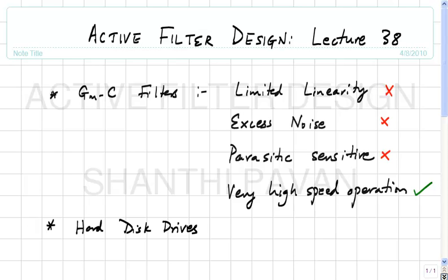So that's one thing. Another thing is that if the disk is spinning at a constant angular velocity, the data rate at the outer edge of the disk will be much higher than the data rate at the inner end of the disk, right. So not only do you have a channel whose bandwidth is varying, it's also a very high speed channel, right. At the outer end of the disk, you will probably be reading data at several gigabits per second today.